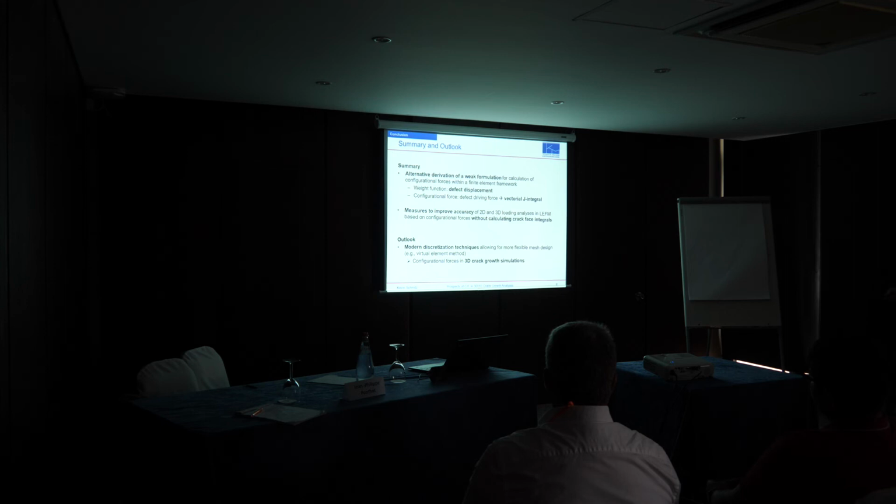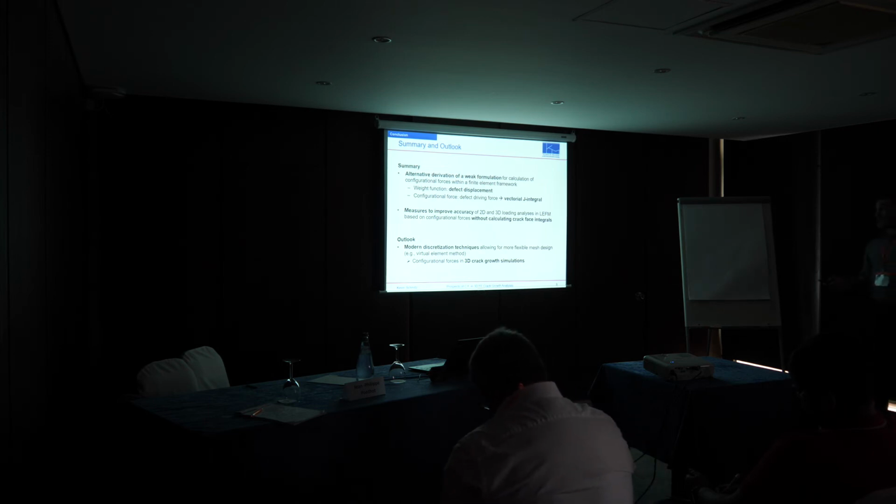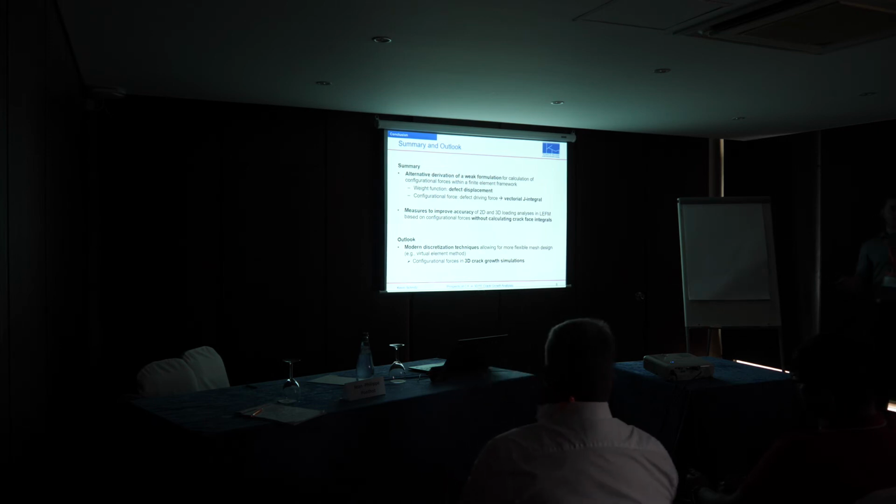So this brings me to my summary. We presented an alternative derivation of the weak formulation for the calculation of configurational forces, where the test function is kind of a defect displacement in our weak form, and this leads to a direct interpretation of configurational forces as a vectorial J integral. Furthermore, we provided measures to improve the accuracy of the calculations without calculating any crack face integrals in the case of linear elastic fracture mechanics.